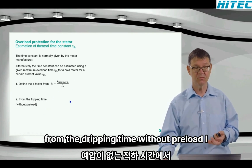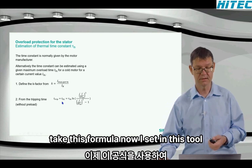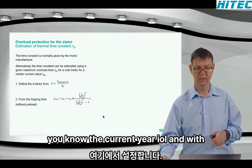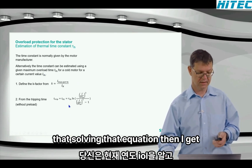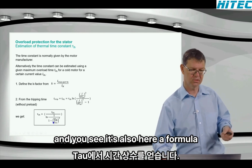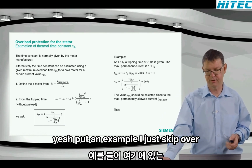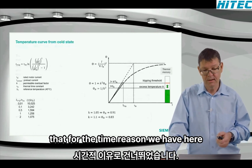And from the tripping time without preload, I take this formula. Now I set in this TOL, this overload time, and here I set in the current here, IOL. And with that, solving that equation, then I get the tau, the time constant, out of that. And you see it's also here a formula with a logarithm in the denominator here at the end. Here I put an example. I just skip over that for the time reason we have here.